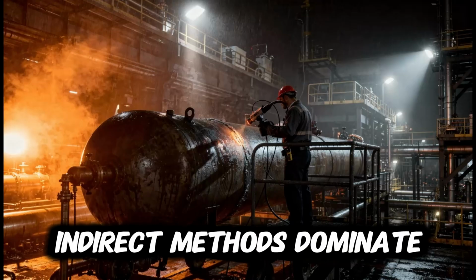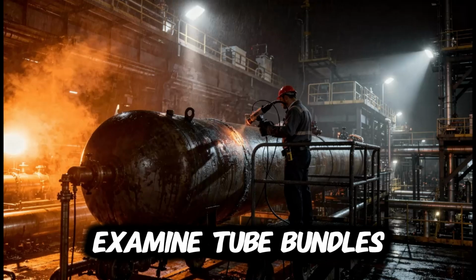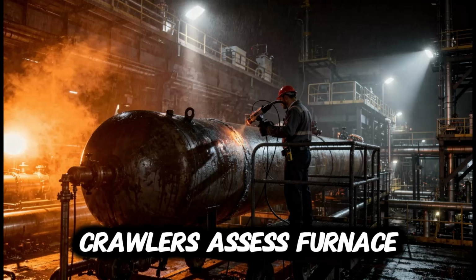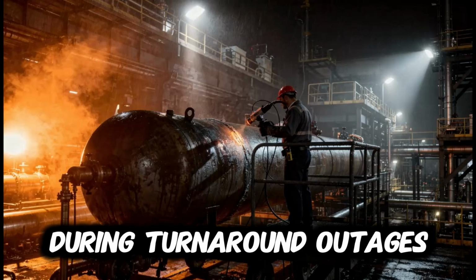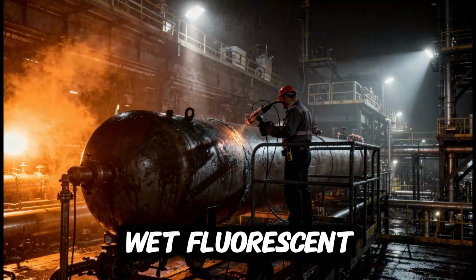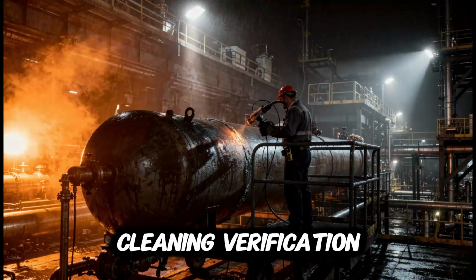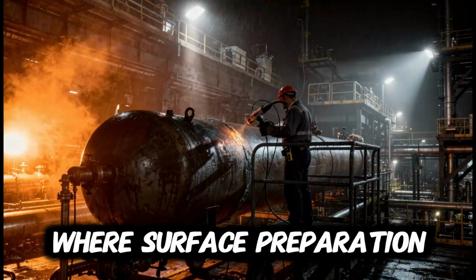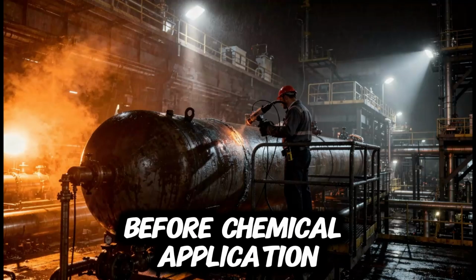Indirect methods dominate internal inspections. Fiber optic borescopes examine tube bundles in heat exchangers, while remote video crawlers assess furnace tubes and reactor internals during turnaround outages. Specialized techniques include wet fluorescent magnetic particle inspection preceded by visual cleaning verification and dye-penetrant examination, where surface preparation is confirmed visually before chemical application.